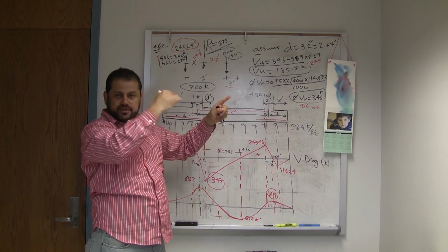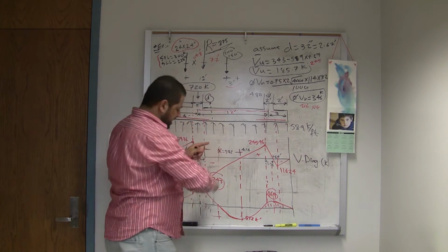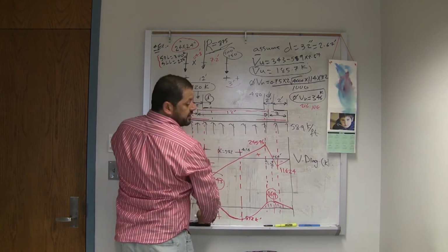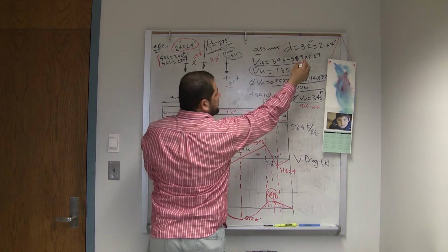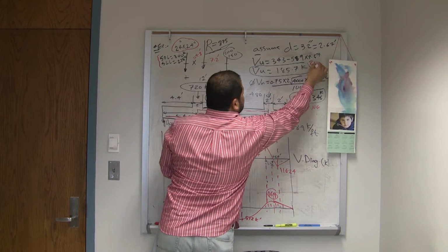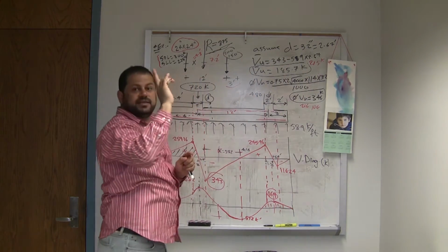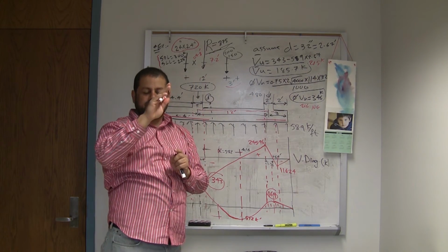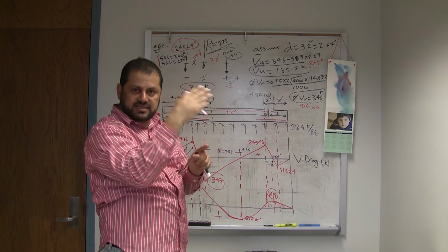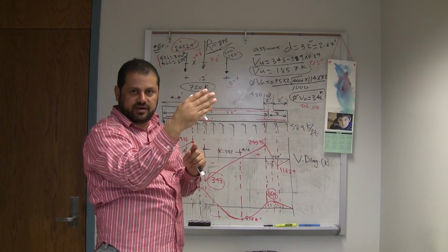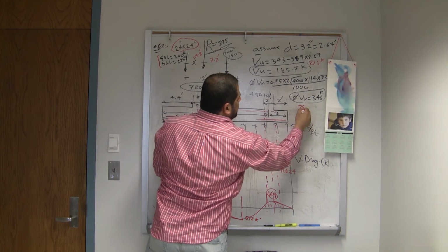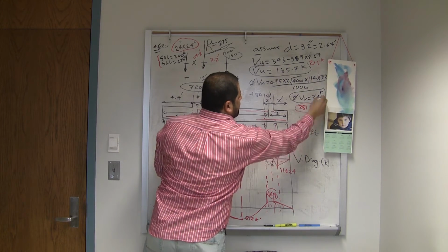So again, we're going to increase it. I'm going to make my footing 30 inch, which is 2.5 foot. For that case, D will be 26. You divide by 12 to get it in feet. So V bar U is 215. The thickness of the footing is 2.5 foot, which is 30 inch, minus the 4 inch cover for D, so you get 26 inch. And this will be 281.